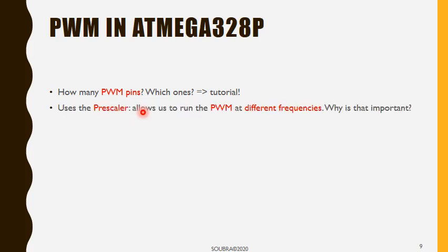All right. To have a concrete example, whenever you're going to control a non-analog actuator, in the sense that it has more than a binary value of on and off, you're going to use a PWM from now on, right? So in the ATmega328P microcontroller, the question is, what pins are connected to the PWM module? What pins are enabled to be used as PWM ports for PWM signals? You're going to check those out in more detail in the tutorial.